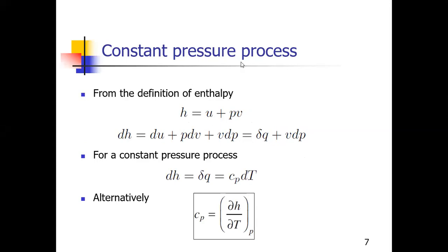So now if your pressure is constant, it means you have a cylinder in which the walls can move. The volume is not constant. So now you start adding heat to that cylinder. Imagine in your mind that you have a cylinder whose walls are movable. Now you add heat to that cylinder, so your gas is going to expand. The volume is going to increase, because that cylinder will try to keep its pressure constant with the external pressure. So that is a constant pressure process. The gas will expand and the pressure will remain constant.